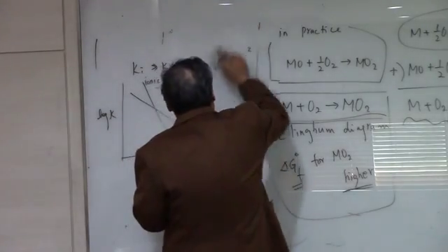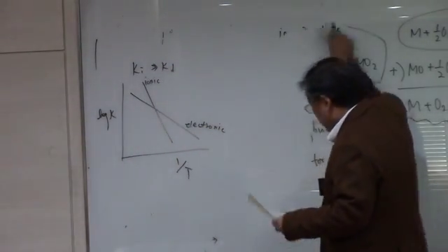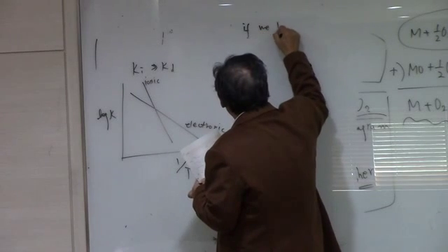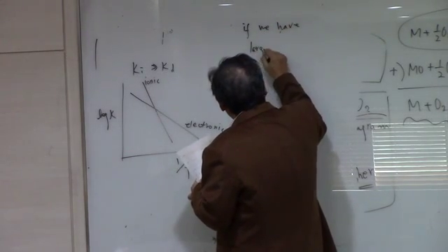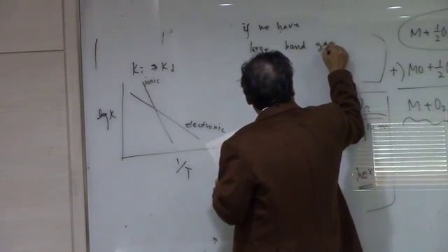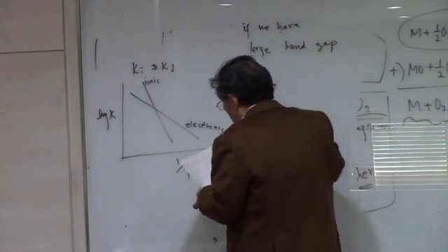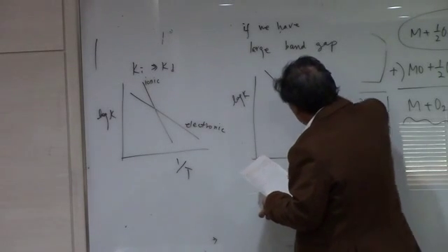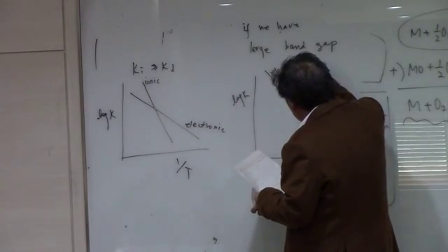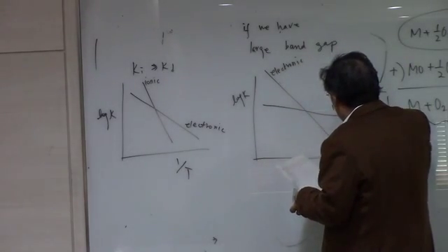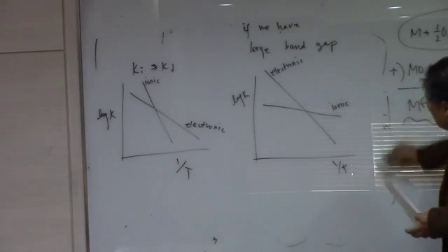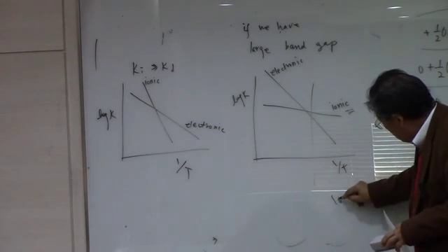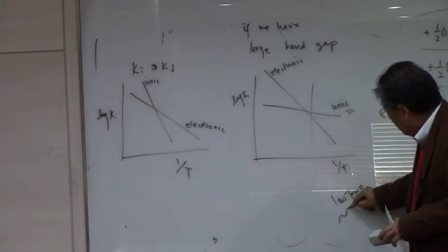And if we have a large band gap material, then this log K versus 1/T is going to be, this is going to be electronic, and this now is going to be ionic. Okay. So in this case, we have ionic materials at the very low temperatures, but it's not that practical.